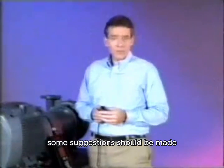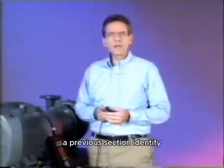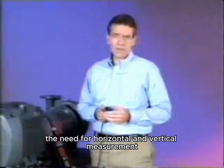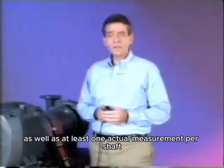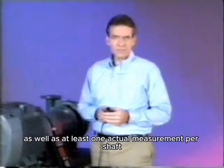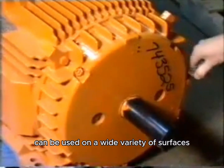Some suggestions should be made regarding the location of collection data points. A previous section identified the need for horizontal and vertical measurement at each bearing location, as well as at least one axial measurement per shaft. The magnet with two poles can be used on a wide variety of surfaces.